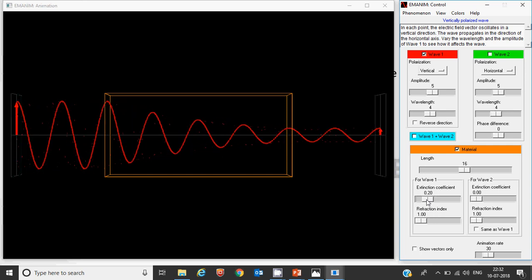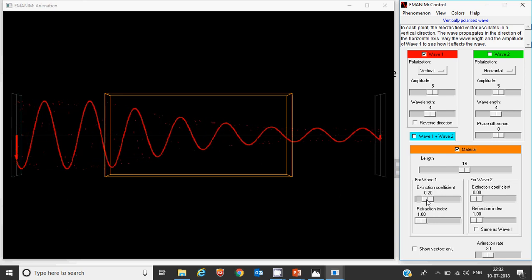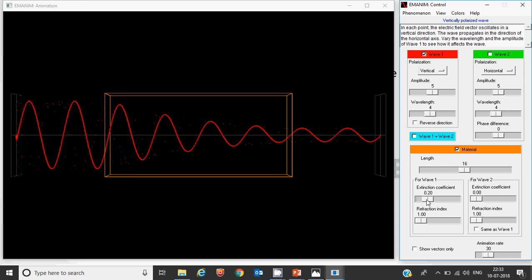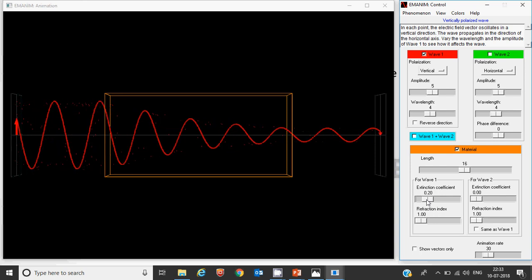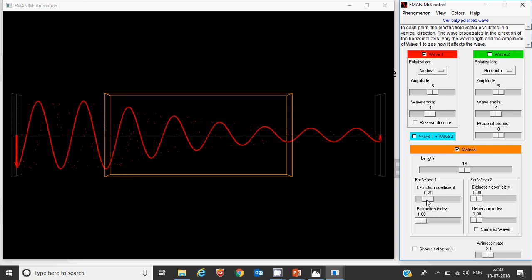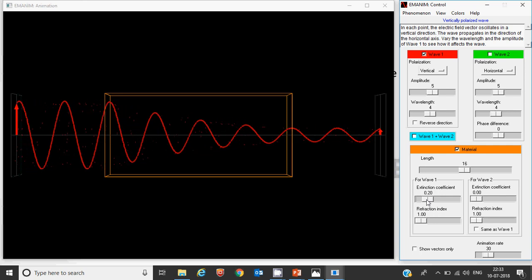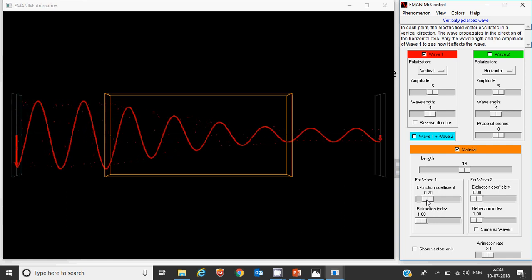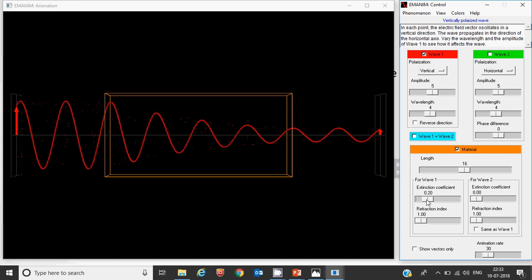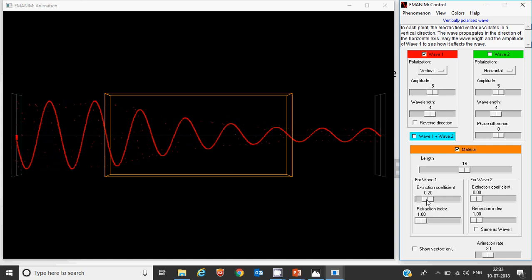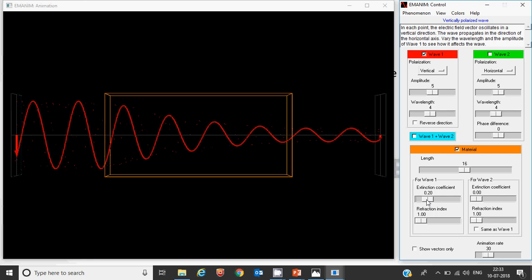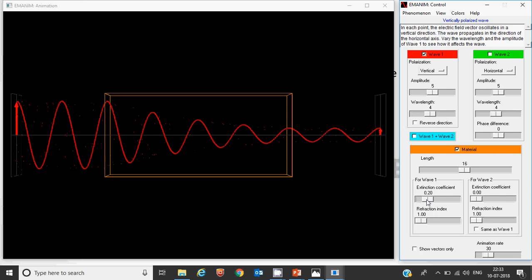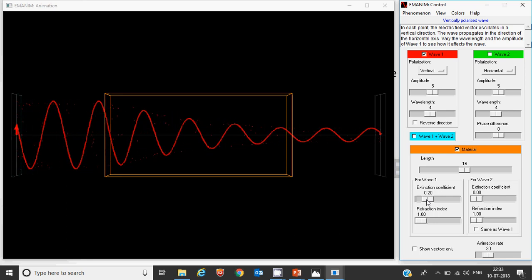So the result is an attenuated wave. So this is called absorption. Bricks, concrete walls, water, all absorb a signal significantly. So absorption is the leading cause of attenuation. The amplitude of the RF signal decreases drastically. It depends upon the medium through which it passes. So that is called absorption.